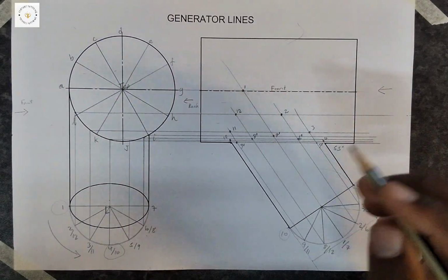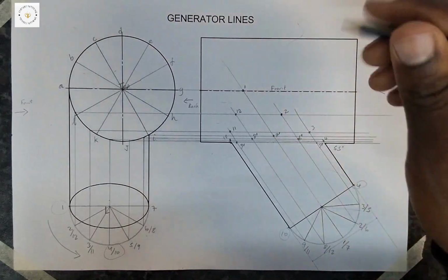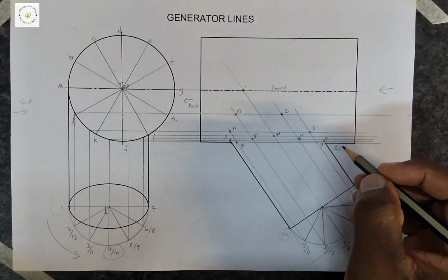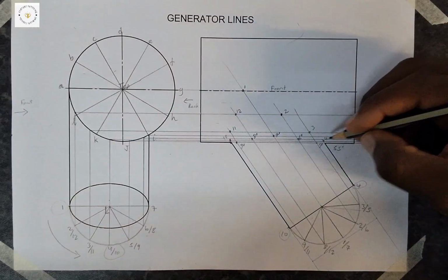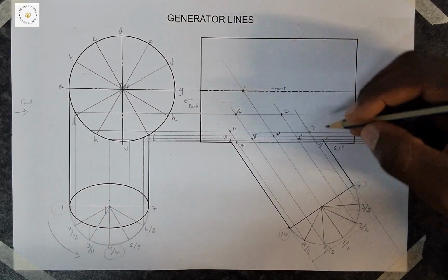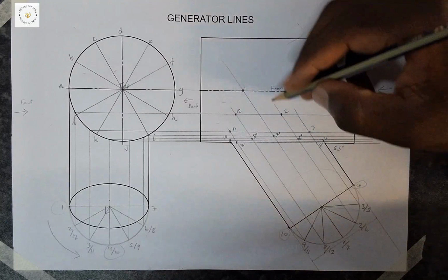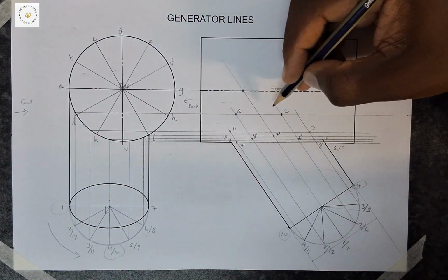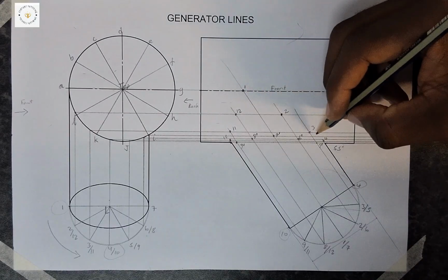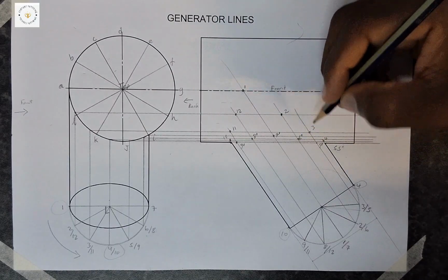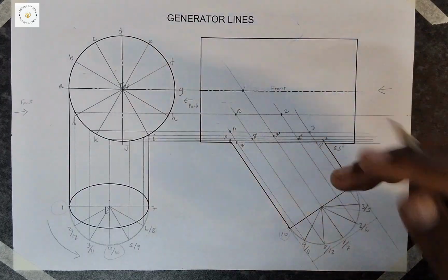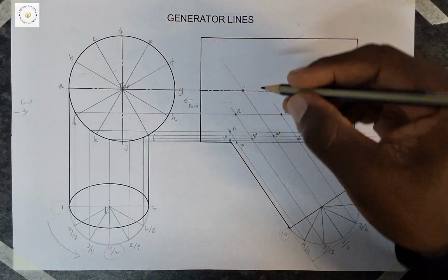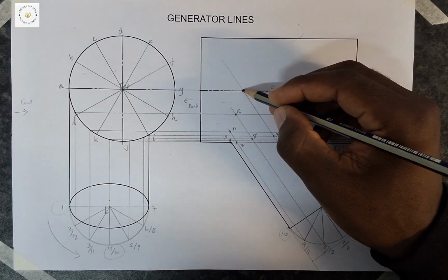So all we need to do is combine the ones without an apostrophe or without the hash at the top. We just combine them, and they need to combine from 10 to 4 or from 4 to 10, and then it's easy to see them, because remember, I already have the tree. I have this, so I just combine them. Try to be a bit curvy, guys, so that you see that it is a curve, because this is a cylinder, when it penetrates in a curvy form. So okay, let me start from here, right?